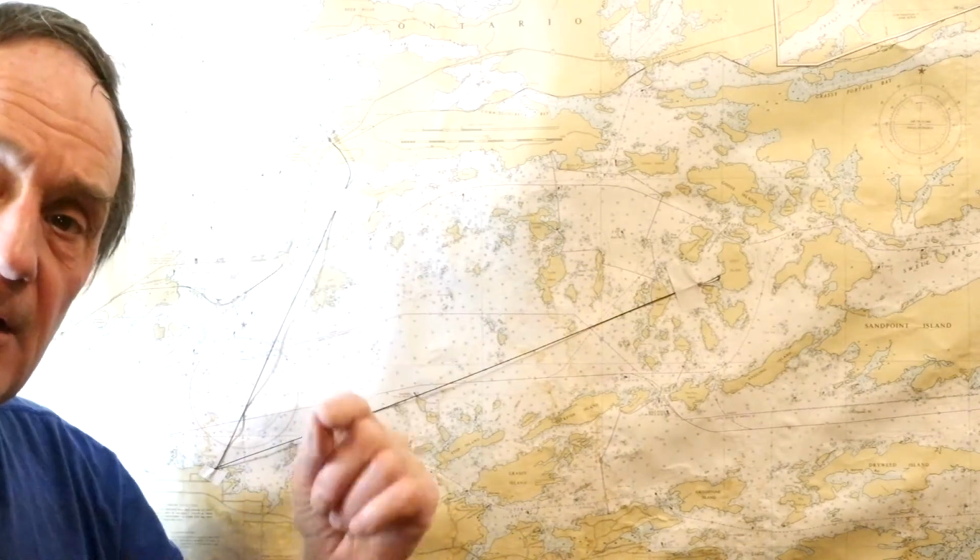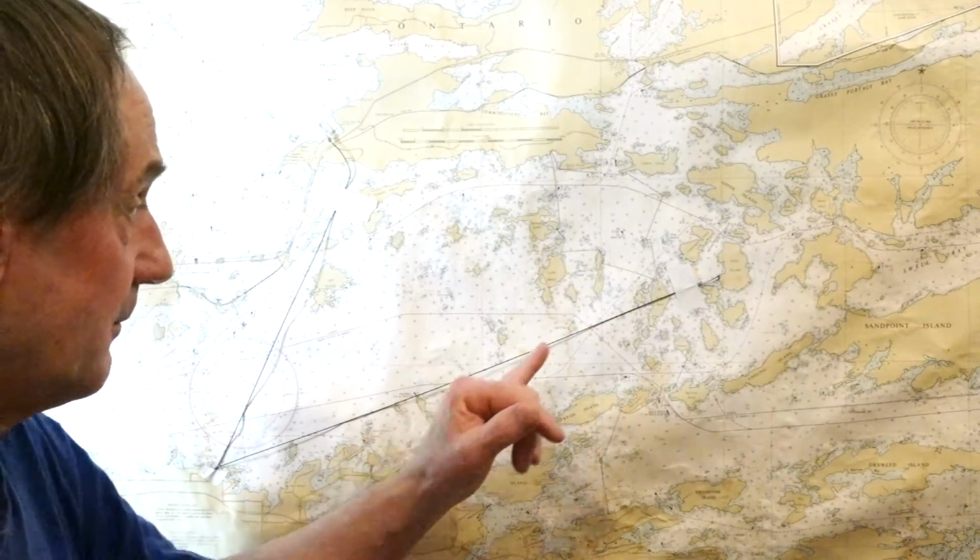And then once the targets are sighted and adjusted, we'll measure the distance from the center of the targets down to the surface of the water. What I'll be doing is drilling a hole at the base of the marker poles to let the water come up through the ice. The water will seek the proper level, the proper height with respect to the lake. The ice is floating on the water, so the ice has absolutely no effect as to the water level.